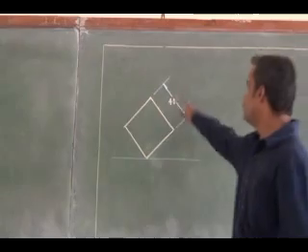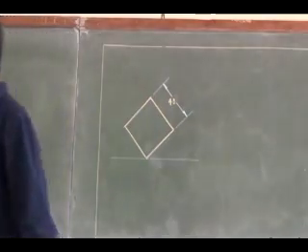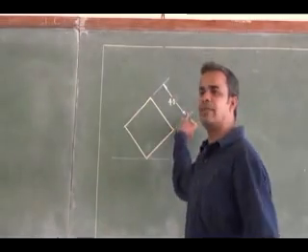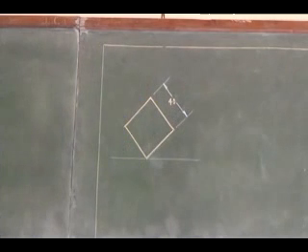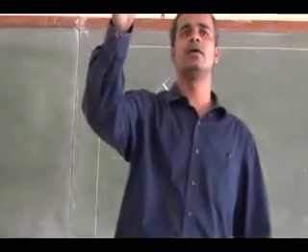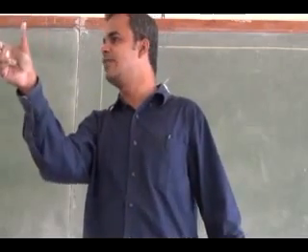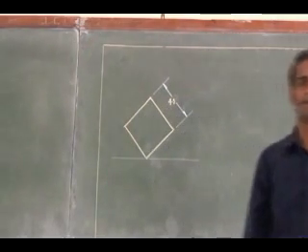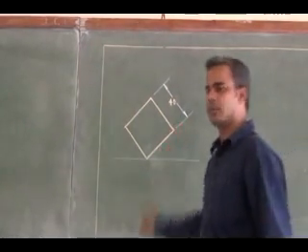Is it clear? Now we carefully put the arrowhead. I will correct the arrowhead otherwise. Right? As small as we put the arrowhead, it should maintain the 1:3 ratio. So the length of the arrowhead can be 5 mm. The height of the arrowhead will be 1.5 mm. That small you have to put. Right? Is it clear? The size of the arrowhead, it should be 1.5 mm to 2 mm. The length of the arrowhead will be 5 to 6 mm. That is the maximum for your drawing sheet size. Is it clear? Okay. Right.